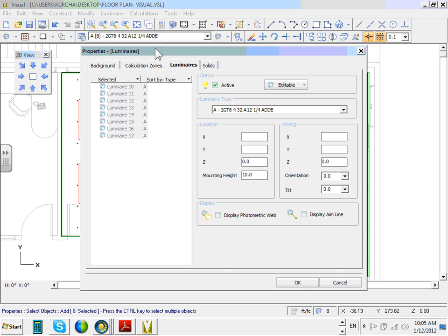Okay, now let's go look at the fixtures. I'm interested in the fixtures, the height. Can you guys see the height? Everybody can see all the fixtures right here. They're gray. This means this height is for all of them. They're set at 10. So actually, if I want to put them at 9, what do you think I do there? Type 9. 12. Type 12, right?